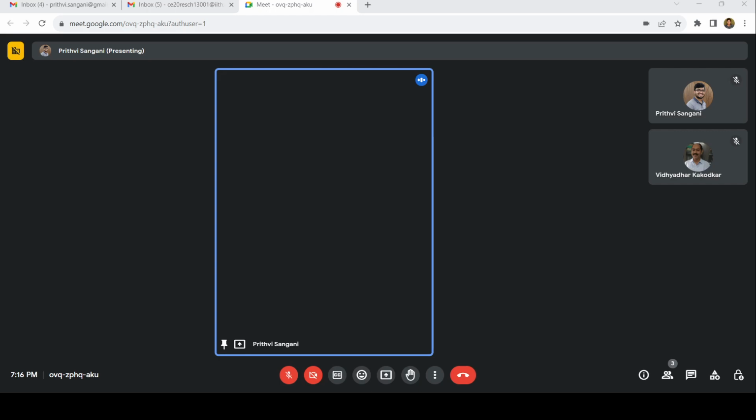So to find out delta 1, what do we need to do? We just need to take the moment of this M by EI diagram at this point, right? So delta 1 is nothing but half times PL by 2EI times L by 2 times 2 by 3 times L by 2, right? Yeah, this is my centroid from here, 2 by 3 L.